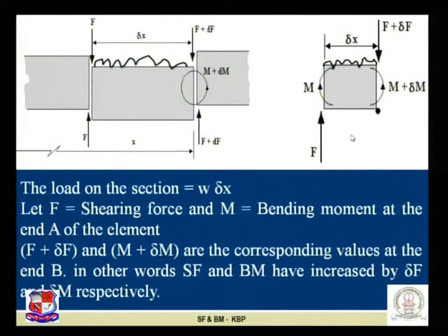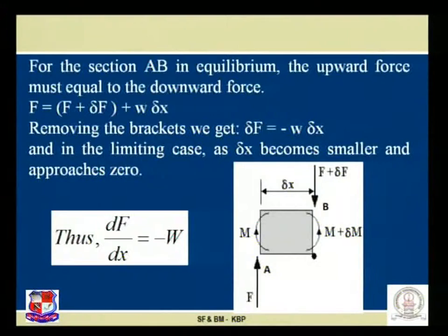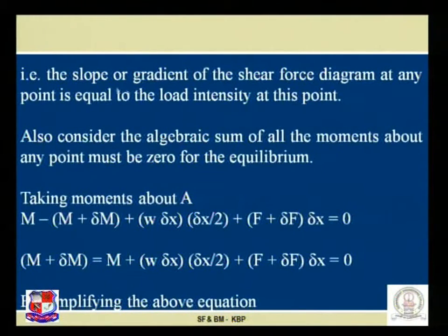So now we have to take the moment of all the forces about section A. Please see this figure very carefully. The first is M. As M is the moment directly given to us, we do not have to use any perpendicular distance, and the plus sign indicates that clockwise moments are treated as positive, the same sign convention adopted since the last series.